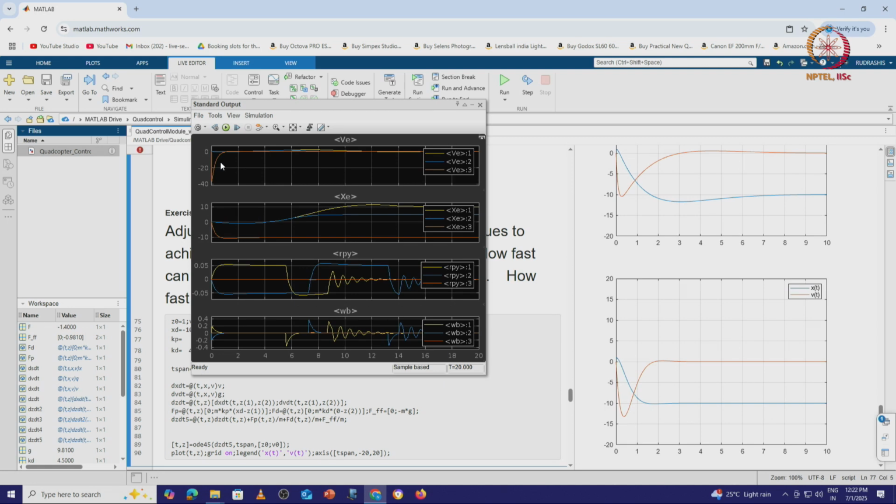Okay, so that way I can understand how to fix these gains and how to give the desired value and get this response as desired by the user, basically zero overshoot and zero steady state error. We can check everything, substitute it, and look at all the control inputs, whether they are saturating or not. All that can be verified nicely in the implementation.